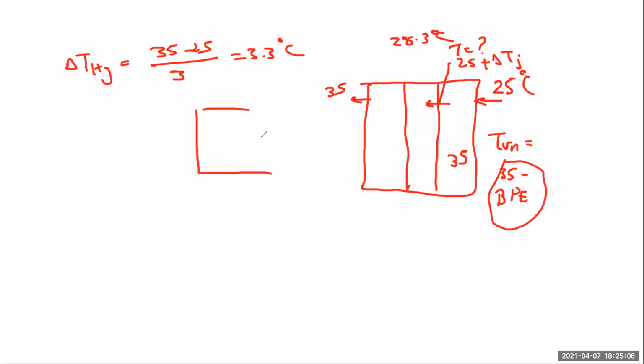Then you can come up with the log mean temperature difference here. For the overall heat transfer coefficient, you are going to take the same value of UC given to you, and then you can come up with the calculations of the area. To calculate Q, you can calculate it from the flow passing here, but in order to do that, you should know the value of m dot cooling water, which we did not calculate and it was not needed, but maybe you can get it from D24.